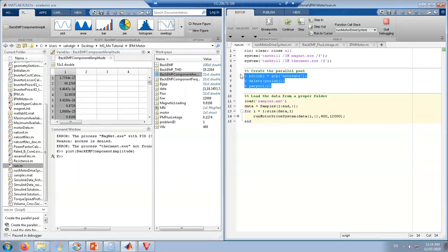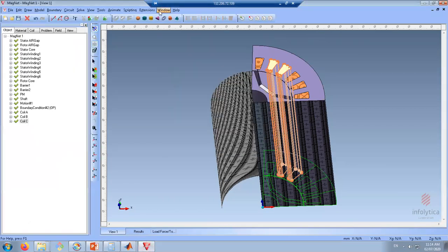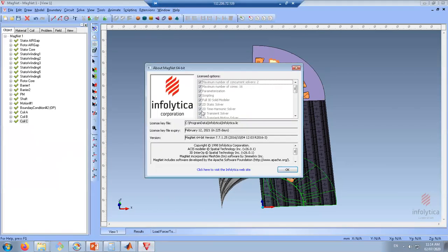Now let's get back to the parallelization of the model. You can just use these 3 lines of code to call the parpool function of MATLAB, where you can deploy the motor submodels on the CPUs on multiple cores. We're going to use only 2 cores of the CPU, because if I'm not wrong, we can only access 2 solvers at a time, right?